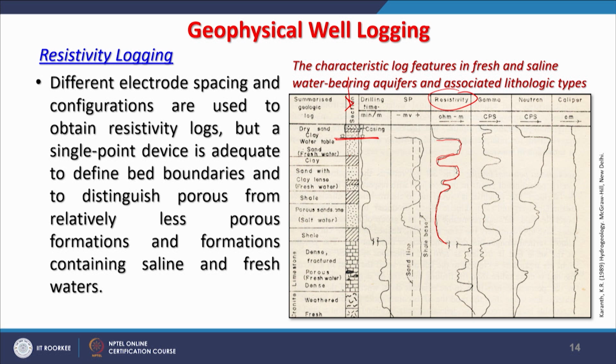In between there might be some changes in lithology. Therefore, it is always good to have a litholog from whatever sampling techniques we have adopted during drilling, along with all these geophysical well logs, which will give you a complete idea about a particular bore well and its characteristics.